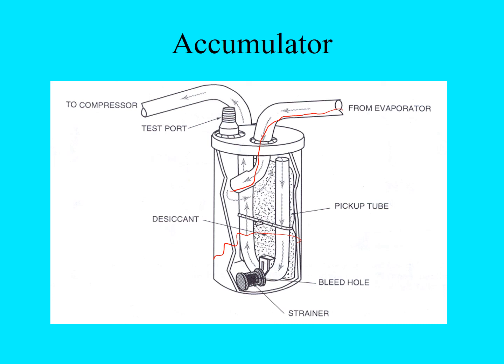The accumulators are large, so just because of that, it'd give plenty of room for the liquid to vaporize before it left and moved on to the compressor. So the gas would move up and then come down through and out to the compressor.